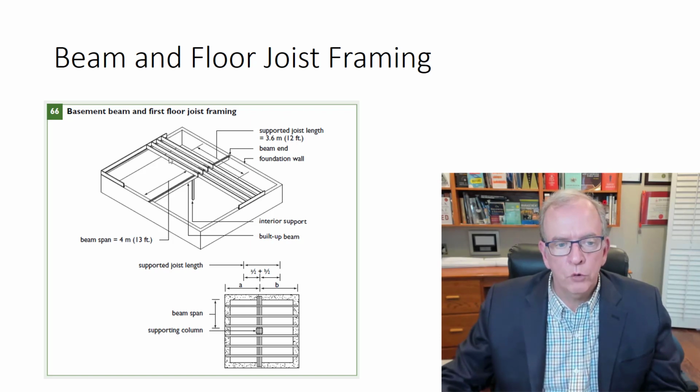And of course, floor joists, which are the horizontal members that are placed on top of the floor. And then we put plywood, which we call a subfloor, over top of it. And so underneath and supporting those floor joists are beams and foundation walls. Now around the foundation wall, underneath the subfloor, we have the joist that goes around the outside, which we call a rim joist.